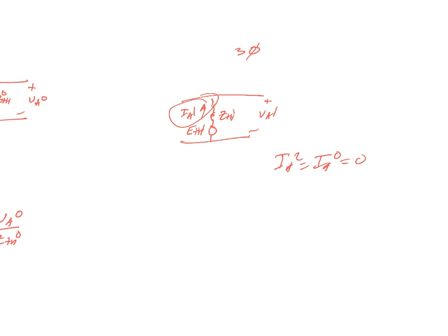So once we have all that information, we've got our networks. Now we can do step 7, which is calculate the faults. And you have to just do that 11 times 3, right? Because you have a single line-to-ground fault, line-to-line fault, and a double line-to-ground fault.